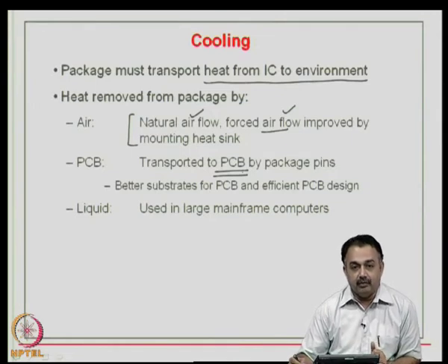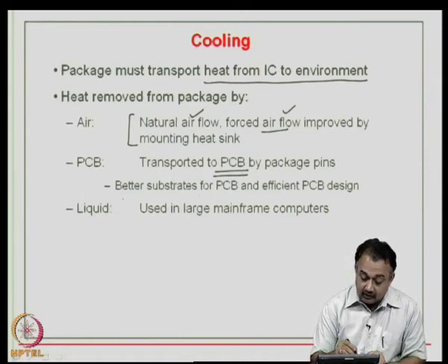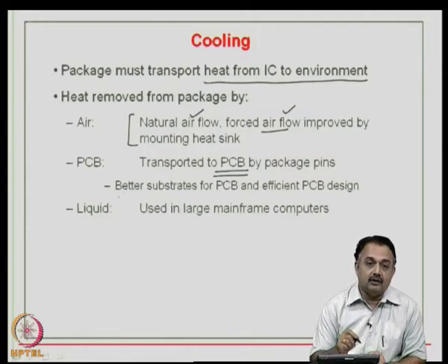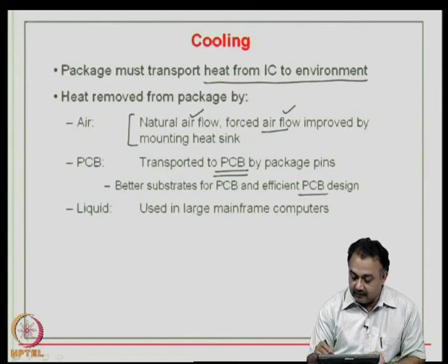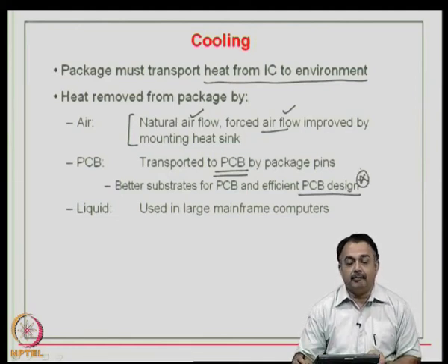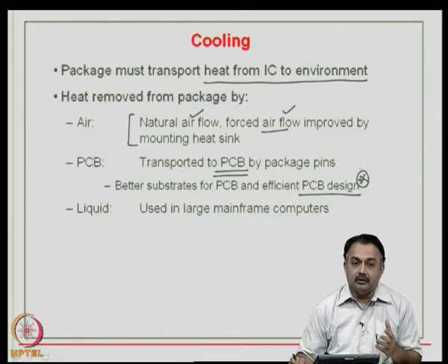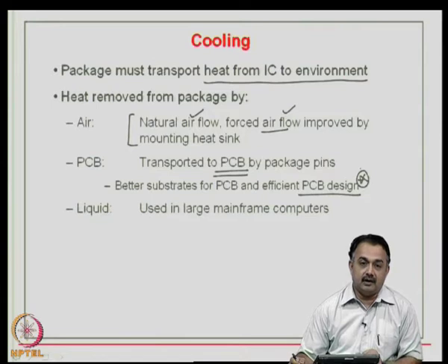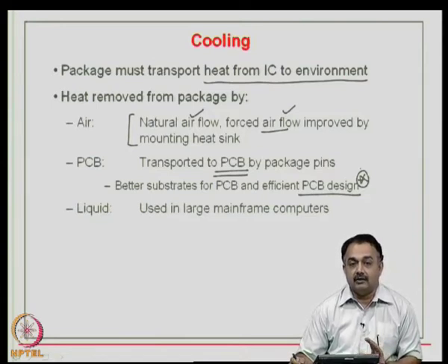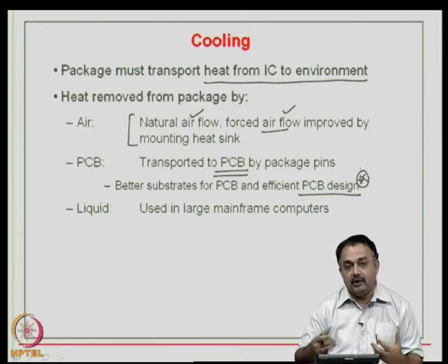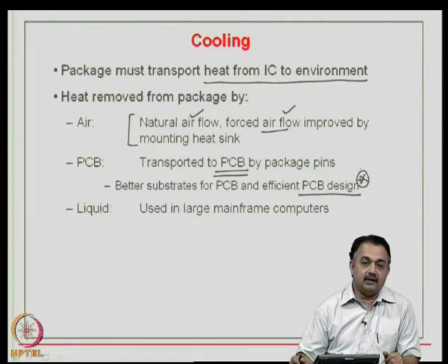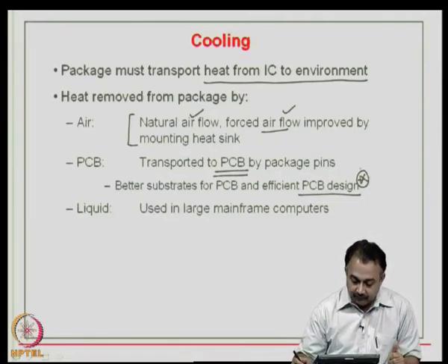Therefore, you must look at the printed wiring board not just as a rigid substrate or a flex substrate that is used for assembling your components. It should also be considered as a substrate that can take care of cooling, removing heat. Therefore, PCB design today does involve a lot of thinking by the designer, engineer, to place your components in such a way that your PCB is not affected and the PCB effectively acts as a good heat sink. There are other methods of designing a PCB where from the package pins you can remove heat through copper layers that can act as a heat sink embedded in one of the layers of the printed wiring board. You could also use liquid.